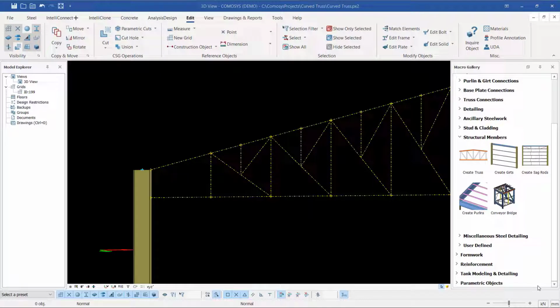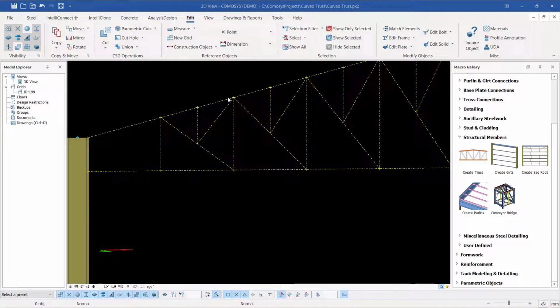This is Morris Dimba on how we are going to create a truss using construction lines as our guidelines. Well, first of all, you create the construction lines to define our truss. You first see how it will look, then you place the steel members. As you can see on the screen here, we had placed the construction lines in place. So what we do is just add the members following the arrangement of these construction lines.